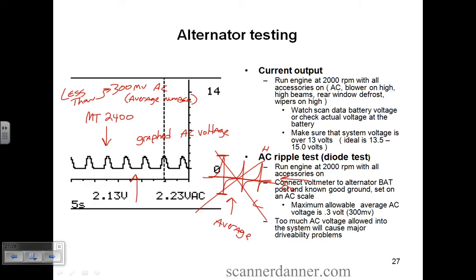And so I get this question a lot, well, how do you isolate that? Well, if you have your alternator and you have that heavy battery post, and then you have another connector here with multiple wires, depends on the design, it's easy to disable an alternator. Don't touch the heavy battery post wire, that one's hot all the time. All you need to do is shut the vehicle off, and disconnect the small gauge one, and then go take it for a ride, which eliminates the alternator from the equation, and see if your problem's gone.